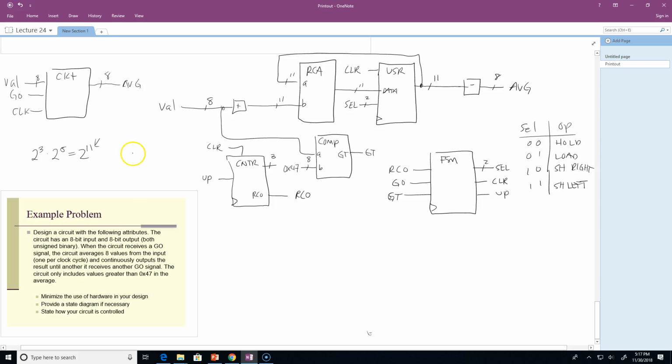I do need to put a note here. Up equals 1 is an increment. Up equals 0 is a hold. Not clear exactly what hold's doing. I need to put a note there. And what else do I need in this thing? I would say clears. Clears are asynchronous. Good enough. I probably should put clears have a precedence over the other inputs, but that's usually a given.